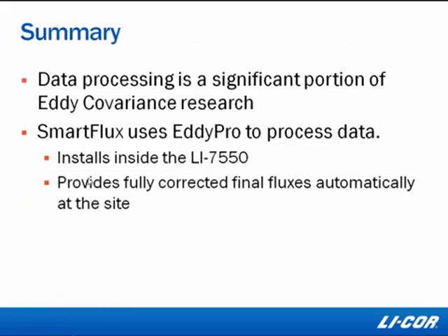So in summary, data processing, as we saw, is a significant portion of the eddy covariance research, and SmartFlux, by using EddyPro, allows us to significantly minimize the effort we need to spend in data processing. And SmartFlux installs that inside the LI-7550, and it provides us fully corrected final fluxes automatically and at the site. And because it uses EddyPro, which is a software people use to get from raw data to publishable fluxes, SmartFlux allows us to get from measurement to publishable fluxes right at the site and in real time.